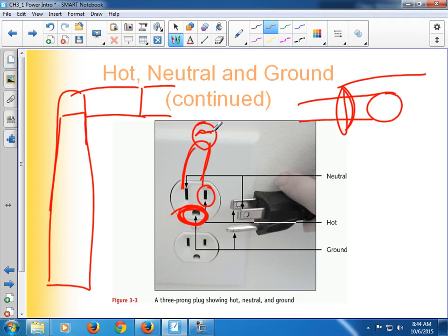Don't ever trust those. If you ever work on electricity, every book you ever read will say turn off the breaker. Don't play with it, because you never know. Maybe this is black and this is white, which is what it's supposed to be. Okay? But maybe it's cross-wired down at the circuit breaker panel. Unless you did it personally, how do you know? Okay? So you have to be very careful with that and turn the breaker off.